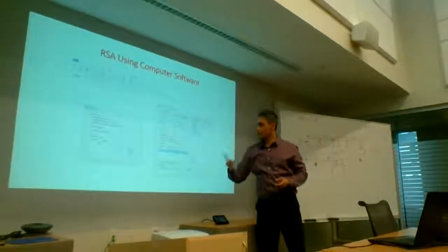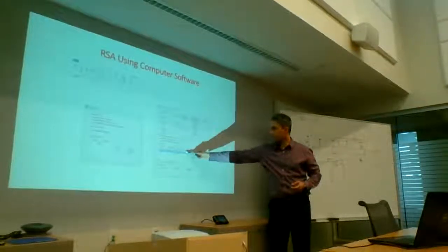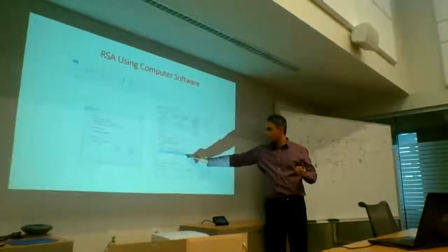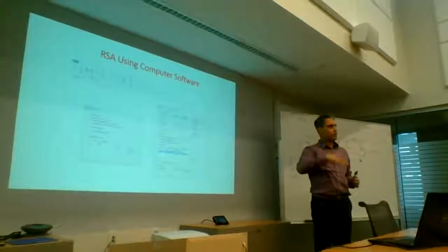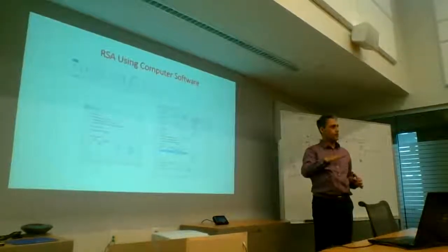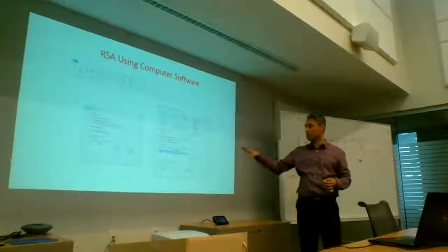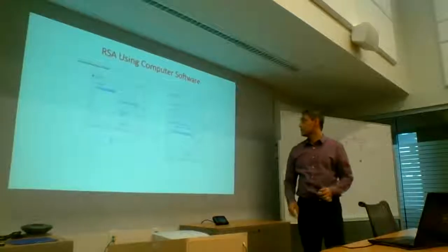So U2 is one direction, U1 is the other direction. For U2, my factor is 9.81, which is 100% of the G. And for U1, I'm taking 2.48 or something, which is 1/3. That's how I'm applying the 30% G in the other direction. That's one load combination. The other one will be the reverse of it. Okay?